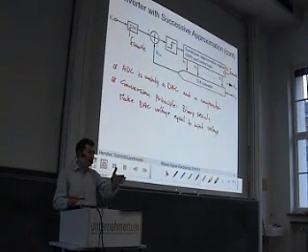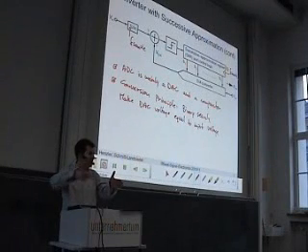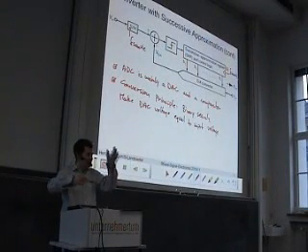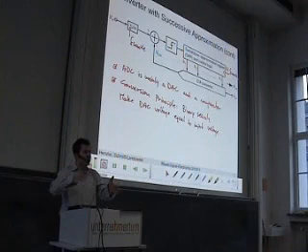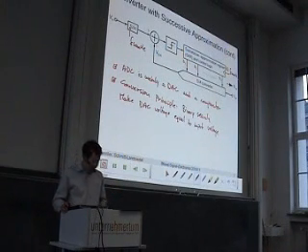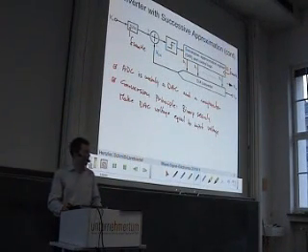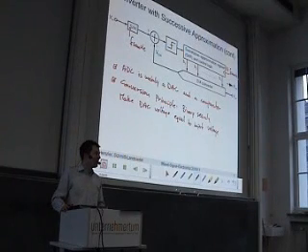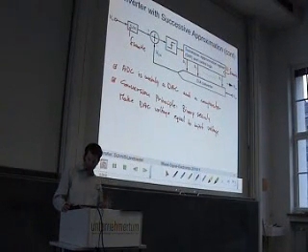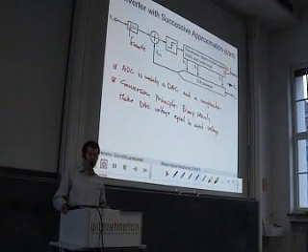Because for each analog sample, we have to perform n cycles internally. And then we take the next analog sample and we have another n cycles in here, where n is the number of bits of this converter. Or if we use a more advanced device with a redundant algorithm, then it can be even more.